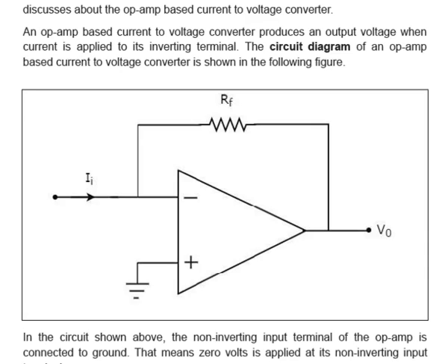So you can see here the non-inverting terminal is grounded, and at the inverting terminal we have applied a current, and feedback resistance RF is always there. So as per virtual ground concept, if this point is grounded, 0, that means this point should be 0.